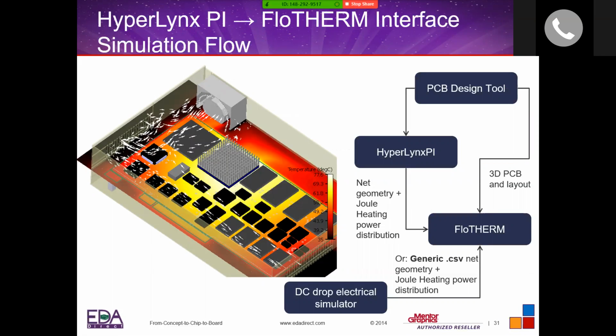Okay. And also, FloTHERM does not work just by itself. Mentor also has the HyperLynx power integrity software. This allows electrical engineers to go in and look at the board layout, look at the power plane, look at the decoupling on the board, and analyze the board from a power integrity standpoint. Do I have enough copper traces?